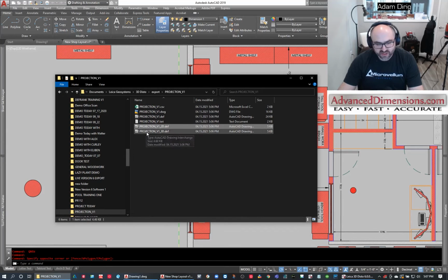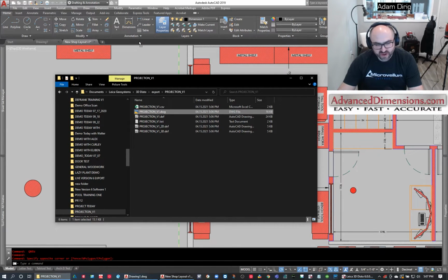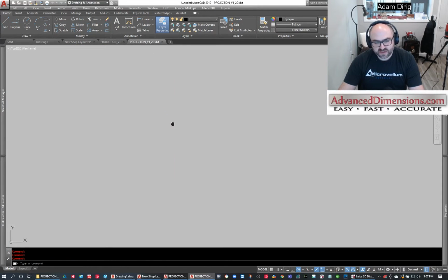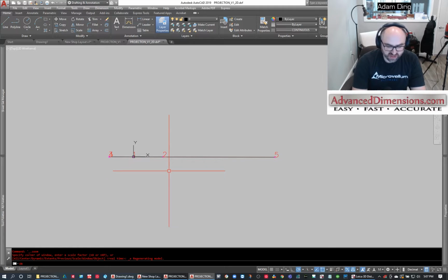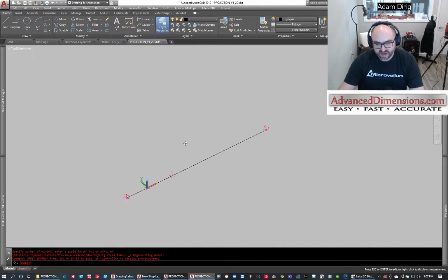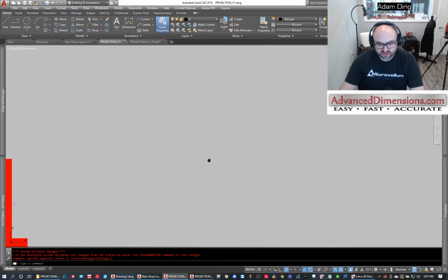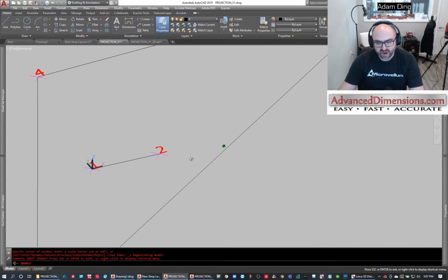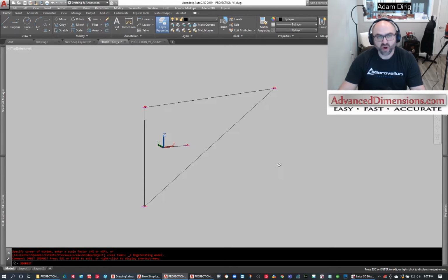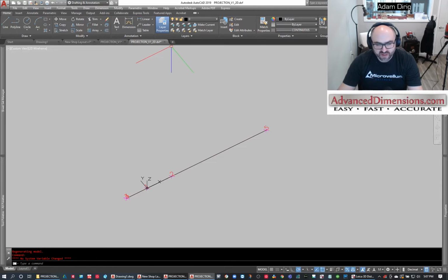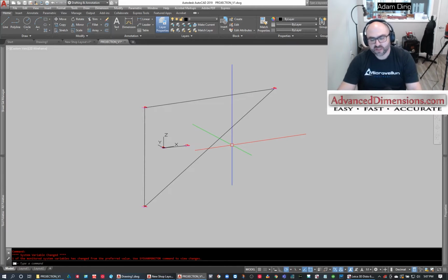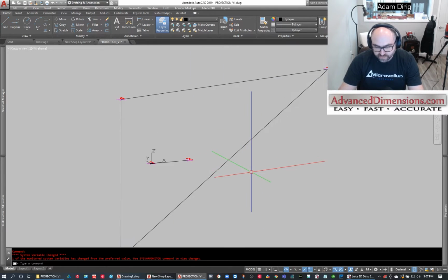So let me go back. So here's my DWG file, and here's my 2D DXF. The 2D DXF doesn't work because it's now just taken everything and flattened it. And when you look at it in this view, it looks the same, but when we orbit it, now we are looking at the wall the way it was, like this. So you gotta be careful. That 2D flatten is not really great in a situation where we're working on something vertically. So here is my wall.